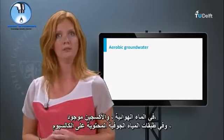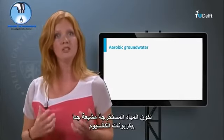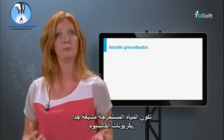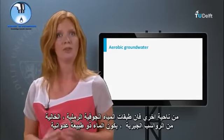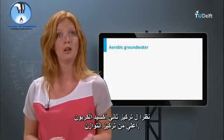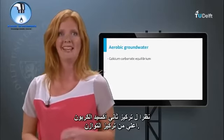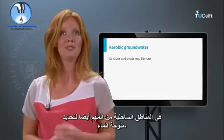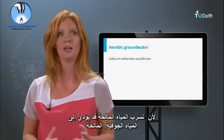In aerobic water, oxygen is present, and in calcium-containing aquifers, the abstracted water may be supersaturated with respect to calcium carbonate. On the other hand, in sandy aquifers without lime sediments, the water can be very aggressive due to carbon dioxide concentrations above the equilibrium concentration. In coastal areas, it is also important to determine the salinity of the water, as saltwater intrusion may result in brackish groundwater.